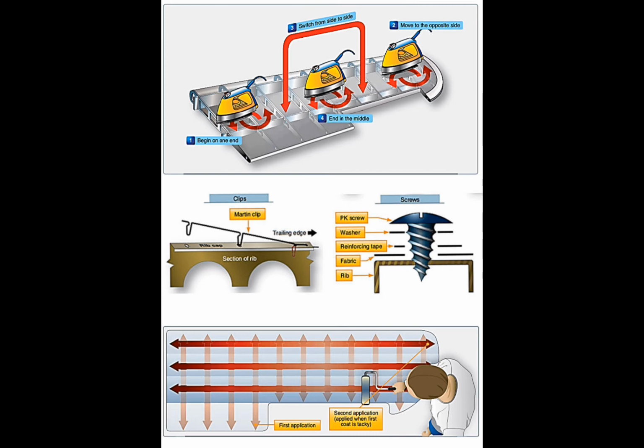What is the recommended type of repair for an L-shaped tear when the legs are more than 14 inches long? Dope on a patch if the never exceed velocity is less than 150 miles per hour.